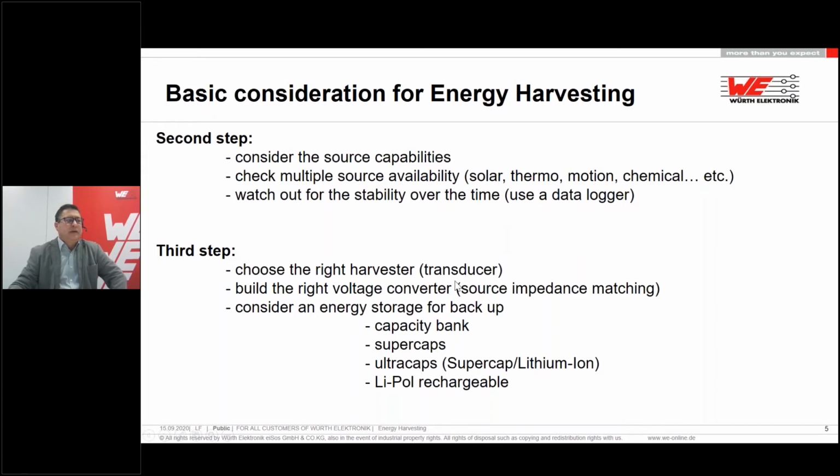The next step is to make a DC-DC voltage converter. Of course, you need good engineering here, because you want to aim for 95% plus efficiency. Then you have to consider where to store this energy. You can store it in a capacitor bank, you can use a supercap, or these kinds of ultracaps, which are a mixture between lithium polymer and supercap, or you can use rechargeable lithium-ion or lithium polymer batteries.